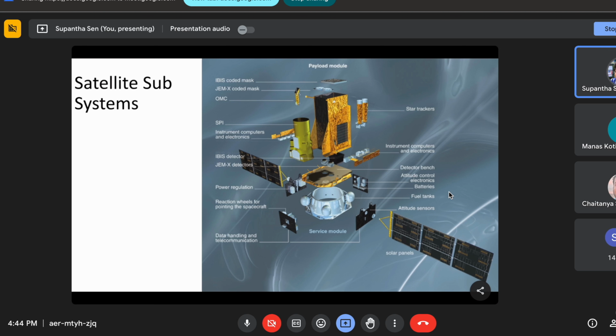So how will you give it? With solid fuel or solid oxidizer, this is called a solid fueled engine. If you use solid engines, you can't control it, because you don't have the freedom of controlling it. Once you light it, the entire solid will burn. You can't control the rate, and you can't stop it in between. So another option is liquid engines.